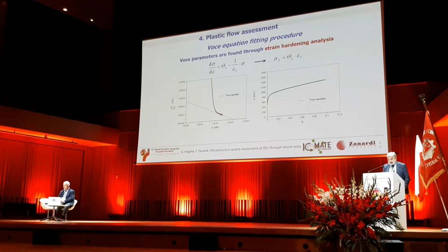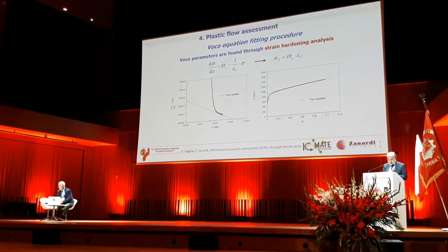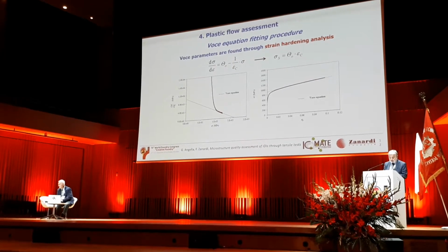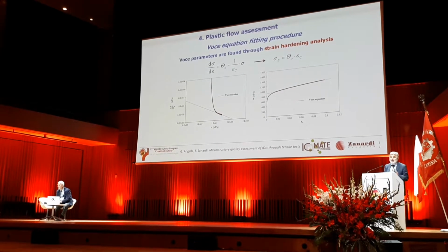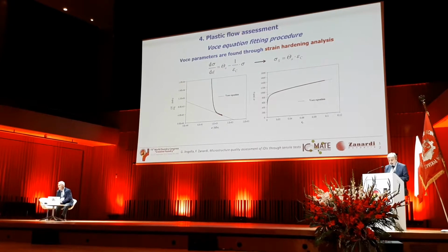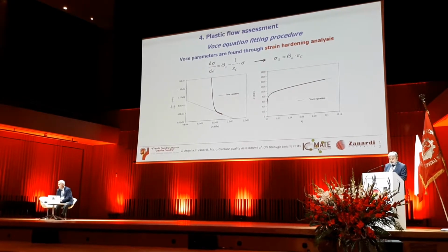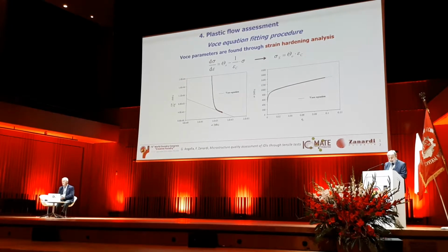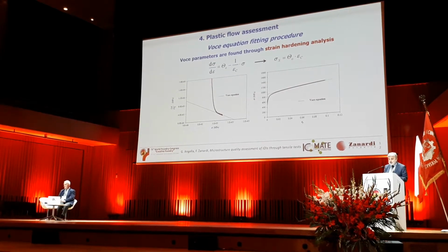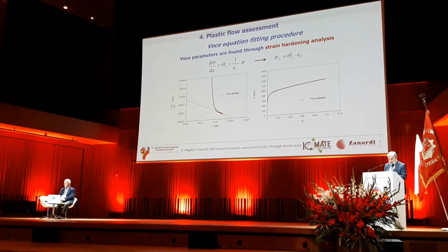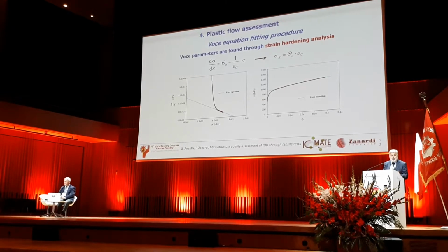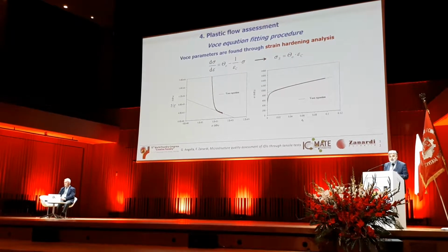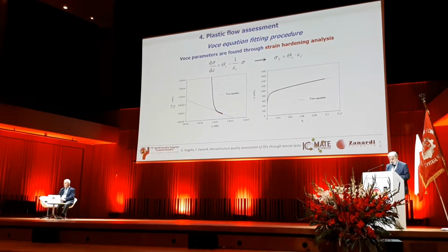This approach is very nice, because on the left diagram there is the representation of the experimental points of the derivative of sigma in epsilon plastic for the true curve, and this analysis is measuring the line interpolating the final points, and so measuring the dislocation motion at the end when you approach the maximum of the engineering curve.